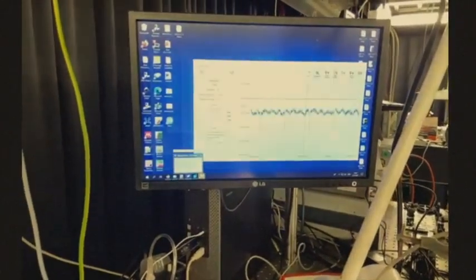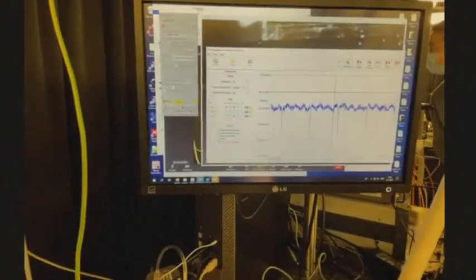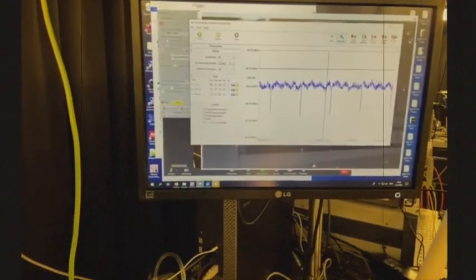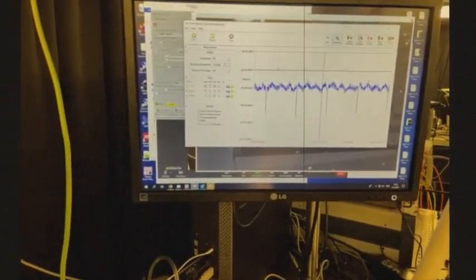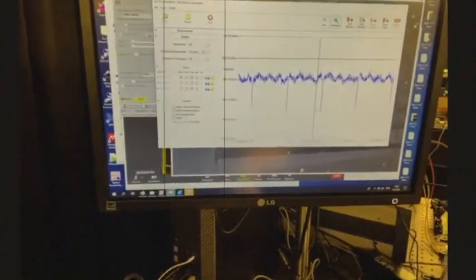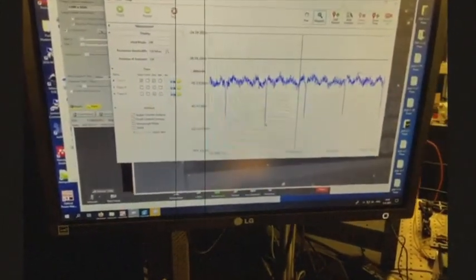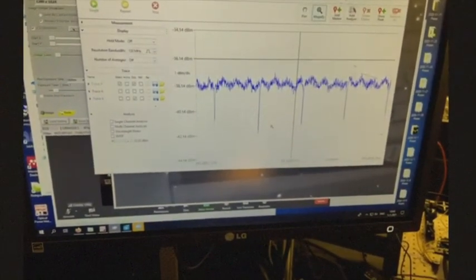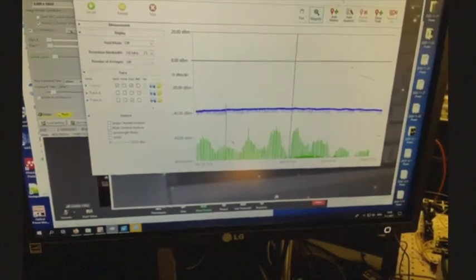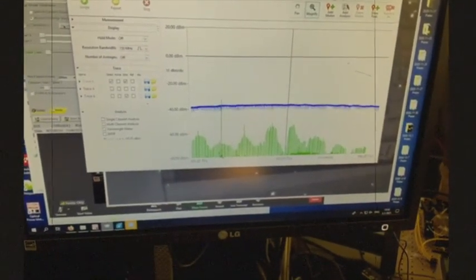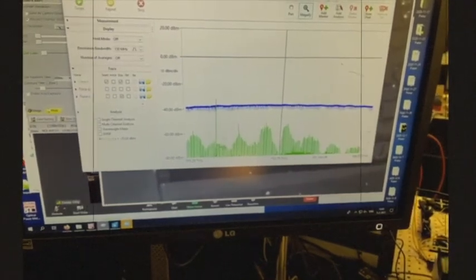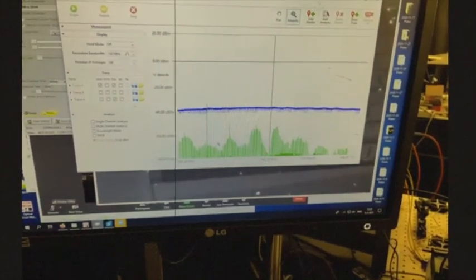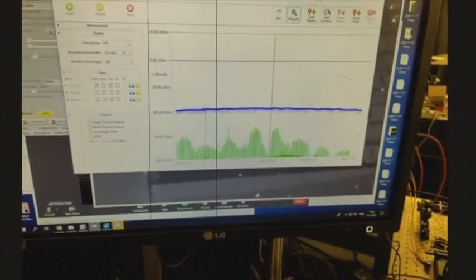Now, for the resonator, here we have some different spectra. These were captured by a bachelor student that worked here with me. He graduated earlier this week. Here we have a few resonances, and at these resonances the light can be created, and this has a bit better resolution. Then you can see below in green a Kerr comb generated, and it has very specific frequencies. In this case, it has a frequency spacing of 25 gigahertz, because the spacing between the resonances is 25 gigahertz in the optical domain.